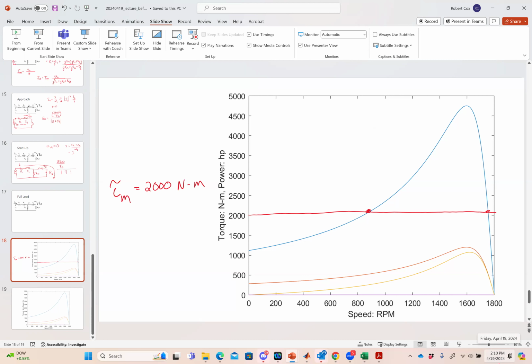So interestingly here, what's supposed to happen? Newton's law, J d omega_m by dt, right, is what? How do we write that? You're used to thinking of the homework you currently are working on, which has a generator. So mechanical accelerates, electrical slows down. If I have a motor, what is it? The opposite of that. Electrical speeds up, mechanical slows down.